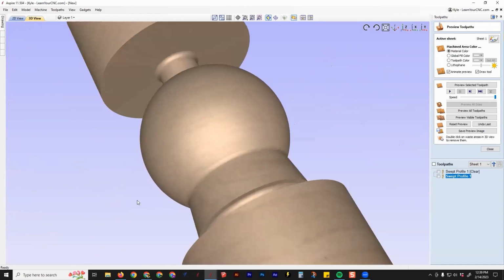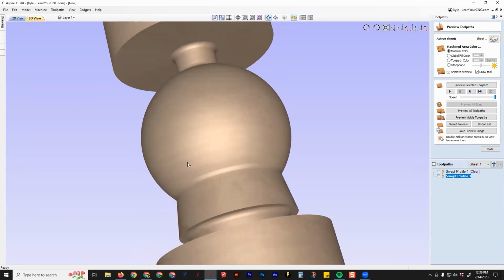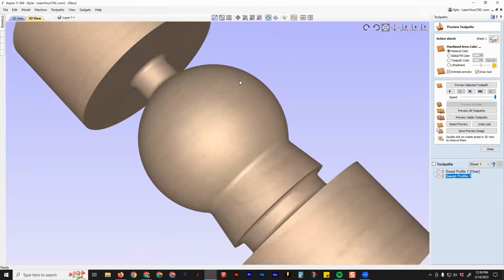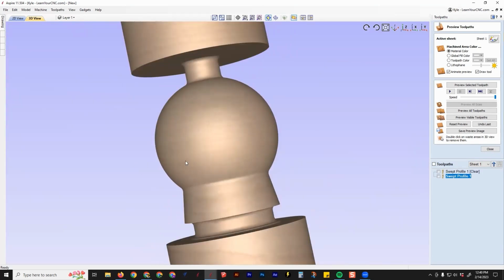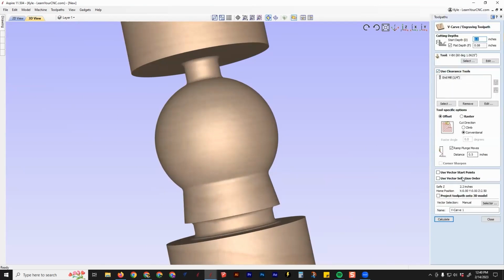The only benefit of doing it in 3D is if you wanted to add like additional 3D objects on top of this. You wouldn't be able to do that as easily with VCarve. You can draw some text. That would only be for the spire because you have to project that onto the 3D model with that option down the bottom. But technically this is not a 3D model, this is just a toolpath. So that option will only work for a spire.